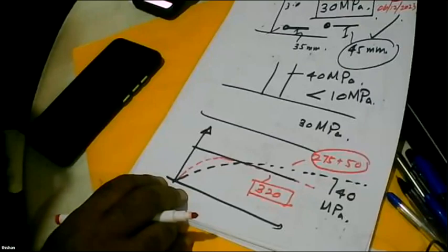Now, fly ash can come into action and continue to react with calcium hydroxide generated by the reaction, and then create a very dense and very strong concrete, and you target 30 megapascal in 28 days. But after about 1 year, if you take a core and test it, you will find the concrete in the raft is 40 or 45 megapascal and continuing to increase in strength.